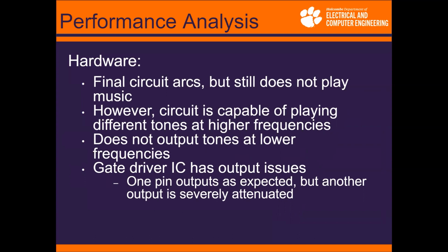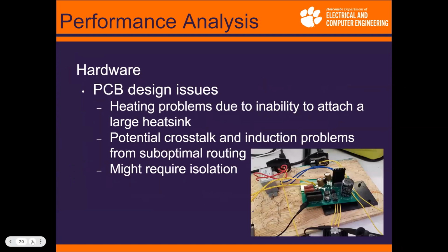Additionally, our gate driver IC has some output issues. One of the pin outputs works as expected, but another one is severely attenuated. We also have some PCB design issues. The way the PCB was routed, there are some issues with attaching heat sinks, so some components get a little bit warmer, but we were able to sort of fix the problem, but the heat sinks aren't large enough to